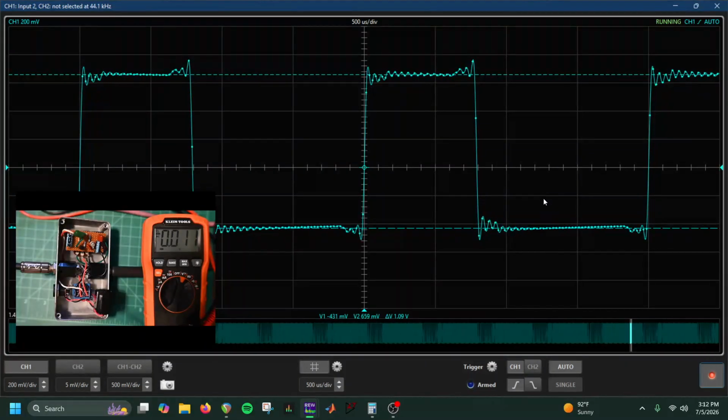So we've got two signal characteristics happening here. We've got the clipping, right? We're just taking off the top of the waveform. And then we've also got this rectification, where we actually see more amplitude on the positive than on the negative. And so these are two critical features of how we create distortion and what type of distortion you actually get out of that.